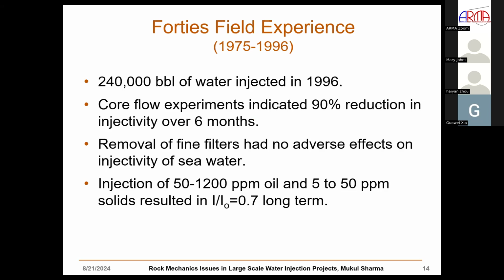Once this was all discovered, once it came to the forefront, fracturing in injection wells became a really important issue, and exactly how this fracturing occurred was an important consideration. So people would thump on the desk in our meetings and say, we never fractured our injectors because fracturing injectors is bad. And I would basically tell them, go back, test your injection wells, and I can bet you that almost all of them are fractured.